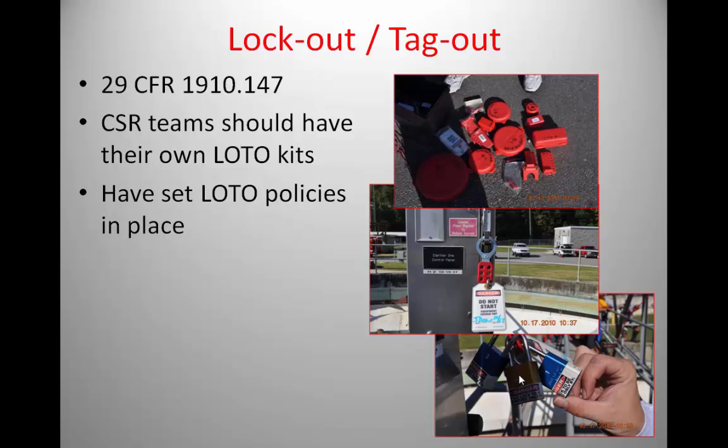Let's say Team 2 comes in, they'll have their lock, they'll put it on. If we fill up all the holes on the hasp, we can simply take another hasp or system and put it in place with the existing. And the advantage of this is when Team 1 gets done with their assignment and comes out, Team 2 is still in the hot zone. They know the system is still locked out and tagged out. So that's the breakdown on how it works. Again, if you want to put your hands on this physically, the SOG SOP file has this, and there's also an excerpt from the policy that's in the lockout tagout kit.